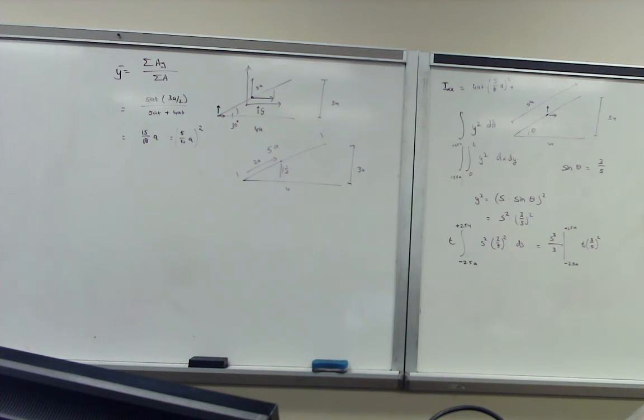Negative 60? Yeah. If you apply this formula here, Ixx is equal to BA over 12 times B squared cosine squared phi plus A squared sine squared phi, this phi angle in our example will be negative 60, if I'm correct.